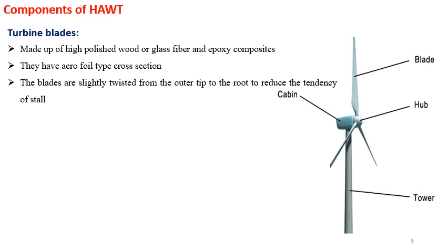So the ratio of the power extracted by lift devices to drag devices is usually greater than the ratio of 3 to 1 for the same swept area. Therefore, drag devices are often capable of generating high torques, that means twisting forces, and are ideal for some uses such as water pumping. So they are less suitable for electricity generation.